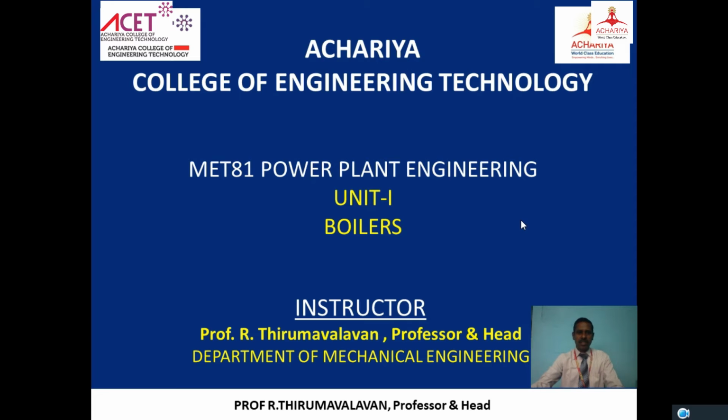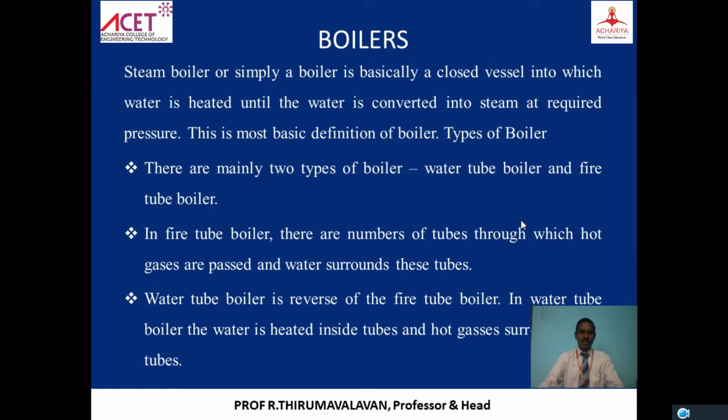Let us get a clear idea about boilers. A steam boiler is basically a closed vessel into which water is heated until it is converted into the required steam. The water is not only converted from liquid form to vapor form, its pressure is also increased. As it is a closed vessel, what will happen? The volume goes on increasing when you are doing the heating process, and because of that the pressure is increased. This is the most basic definition of the boiler: a device which converts water into steam at the required temperature and the required pressure.